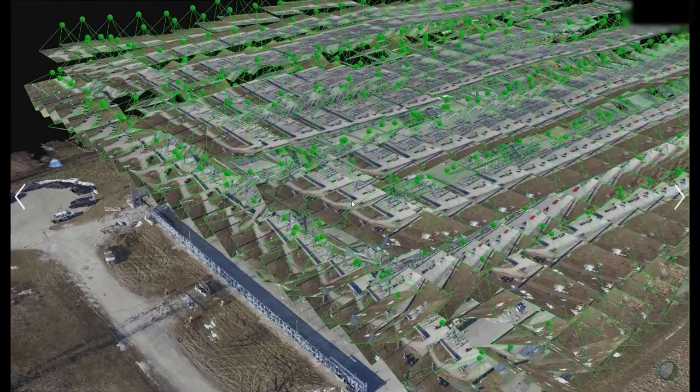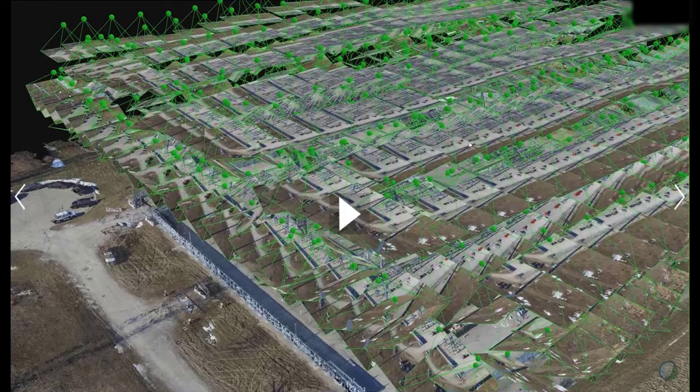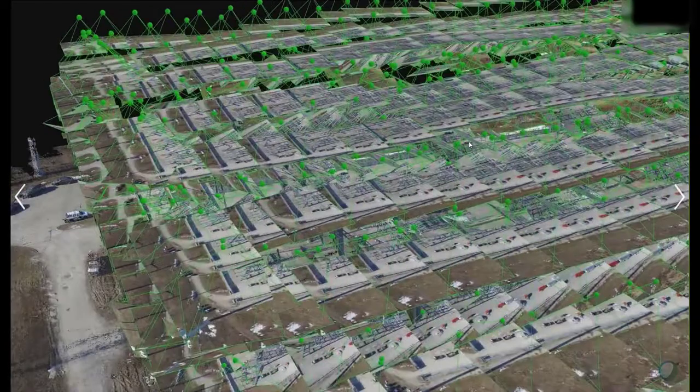So what you're looking at is the output of a UAV scan. Okay, so all these green dots you see are where a drone has acquired one single high-resolution photograph. Okay, so the flight of this drone is very, very prescribed. It's a very particular altitude, very particular percentage of overlap. All those parameters are designed. The drone is flown autonomously in sort of just a snaking pattern, just periodically snapping these photographs.